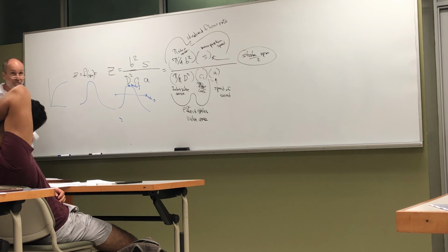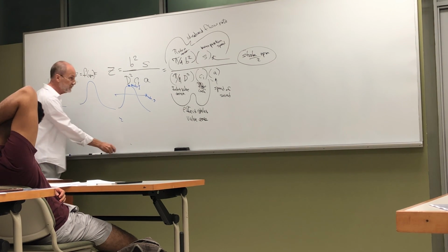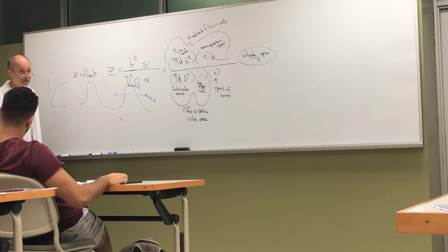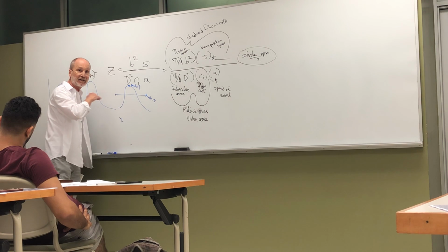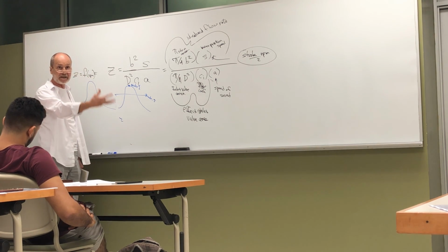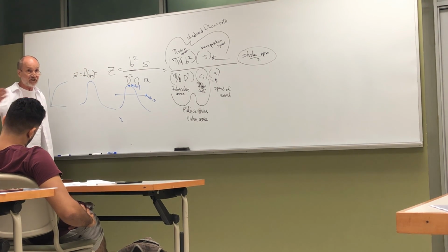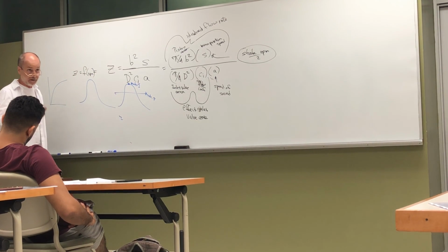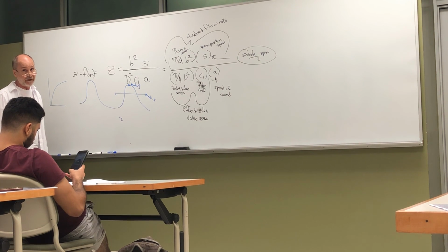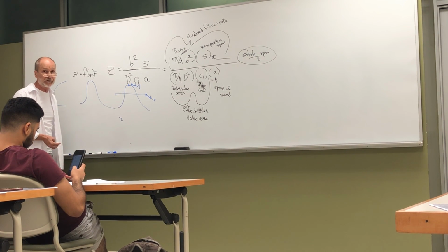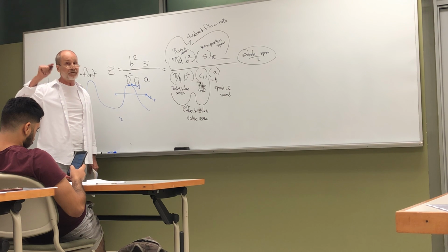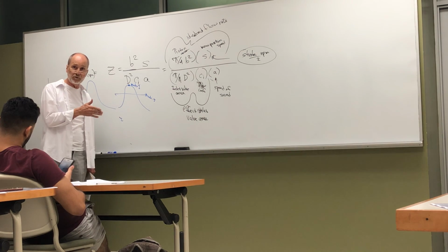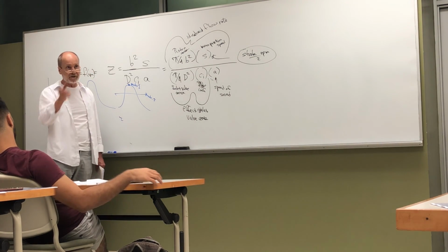So at Mach 0.5, we begin to experience a drop in volumetric efficiency because this portion of the intake stroke, even though we dropped the pressure lower in the cylinder with a higher RPM, cannot deliver more mass flow. We can't get more gases in the cylinder. And as we go to still higher RPM, this is a larger portion of the intake stroke, and we get to where we have a very small amount of fuel and air in the cylinder at a high RPM with a lot of friction, and we're not making any more power. So it's time to shift and go to a new gear, drop the RPM down, and go to the range again.